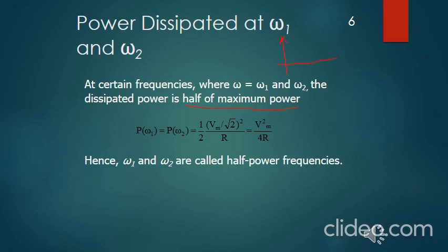Just look at the sketch I have drawn here. That is the sketch of a resonant circuit characteristic, frequency or angular frequency omega versus voltage or current curve. As we know, at the resonant frequency, maximum current or voltage passes through the circuit, I maximum, in that position. So the curve runs through like this. Whether there is a high quality factor or low quality factor doesn't matter, but the curve will largely look like this.